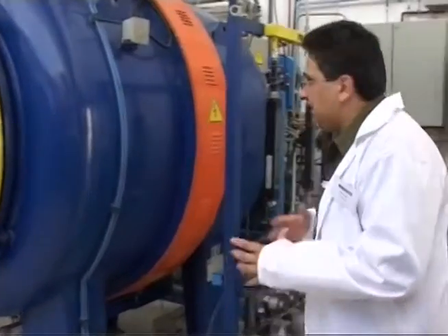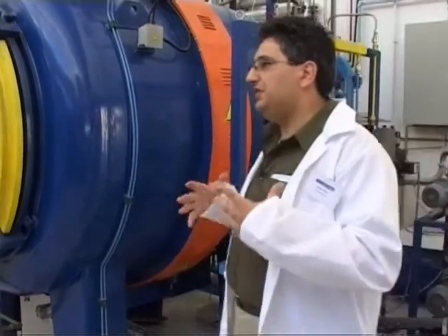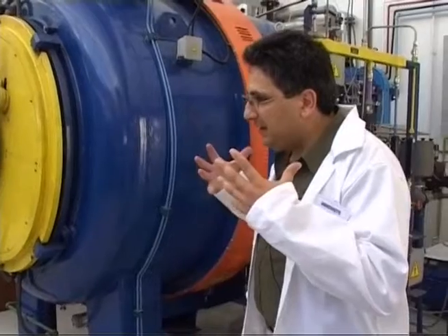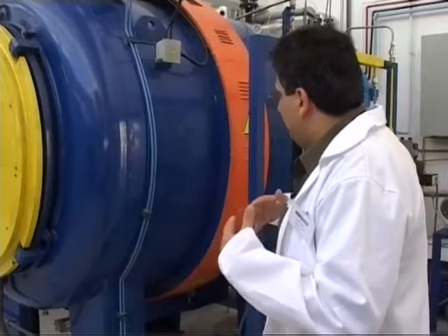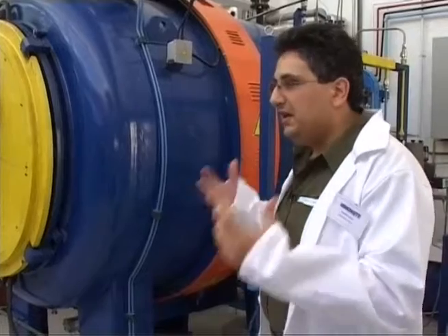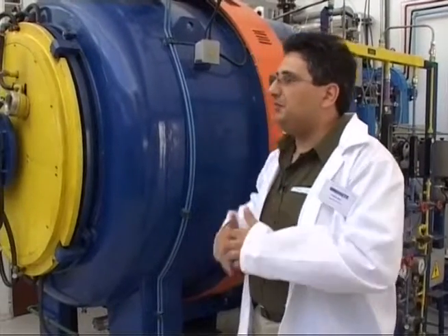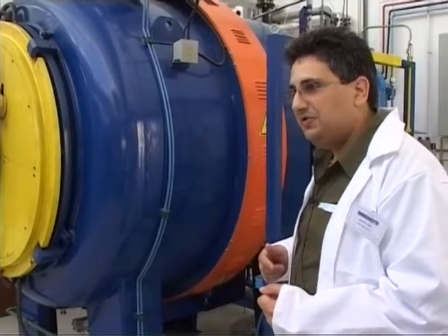This furnace over here is capable of a number of surface modification techniques, some of which are pre-oxidation, which is an aggressive chemical attack on the surface intended to increase the surface area of the material. I will explain further why that is. We can also passivate the surface to render it more inert to atmospheric corrosion, thereby extending the component life. Gas nitriding, which is a thermochemical process.